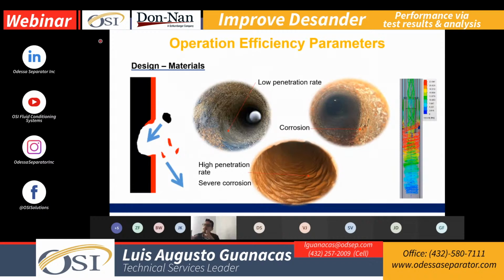So when you don't use the proper material for your downhole conditions, you will have this result. And if we combine this problem with the sleeve length that Shivani just talked about, we will have two problems, because normally the tailpipes are weaker than the sleeve that this desander uses. So when this centrifugal force is moving down and reaches that tail joint, the first tail joint below the sleeve, you will have sand coating in the tail joint, and probably you will have a fish problem. So it is very important.